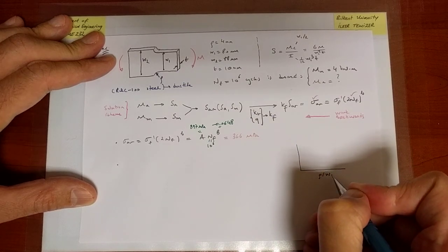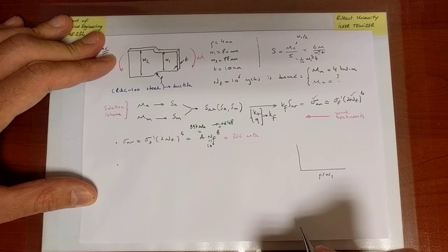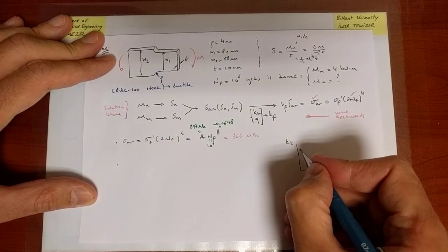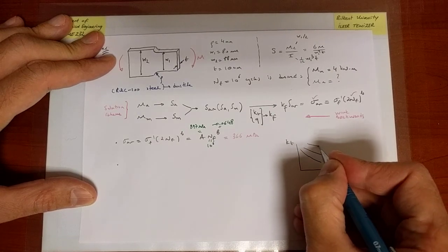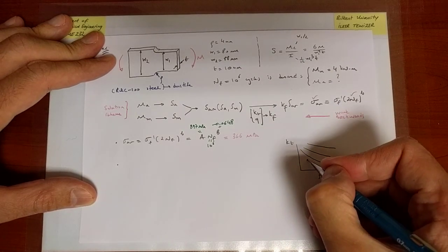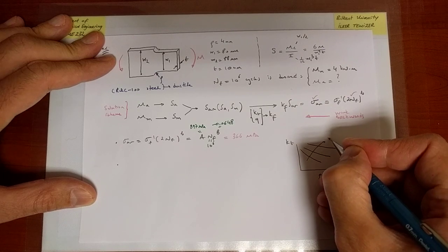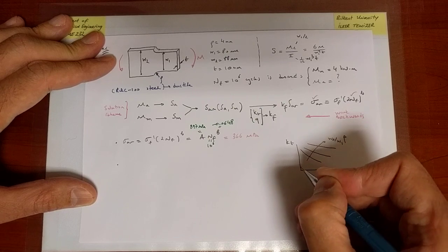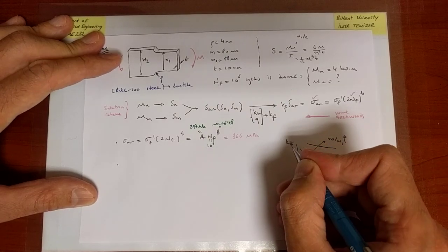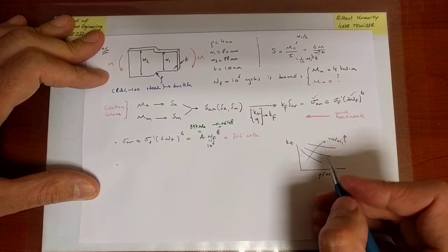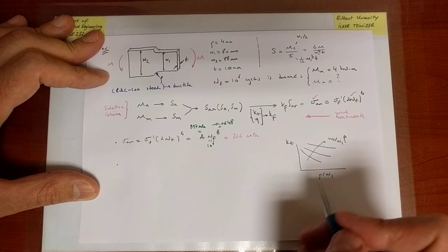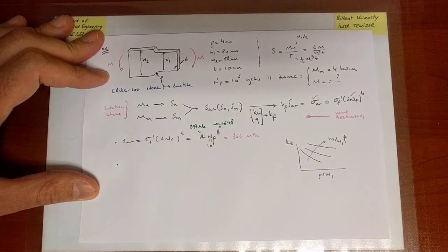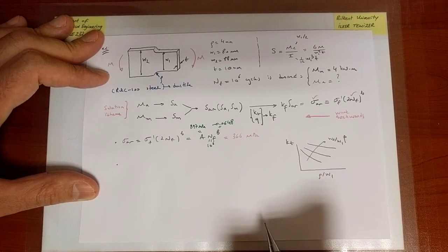For this particular case, it's a function of rho over W1, and we read the value of the corresponding KT from figures like this, in which each line corresponds to a particular value of W2 over W1. As the ratio increases, the situation becomes more critical because the transition in the geometry becomes more severe and the KT value increases. So I need to go with the correct values of W2 over W1 and rho over W1, and this figure is provided in the appendix.